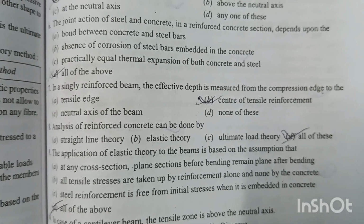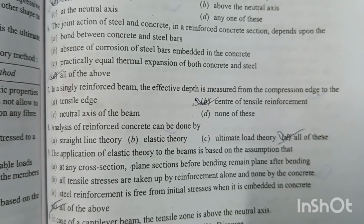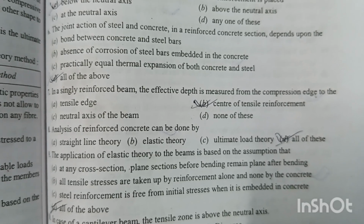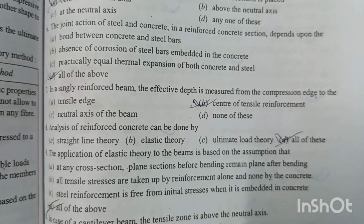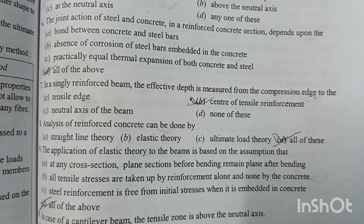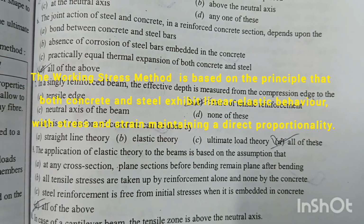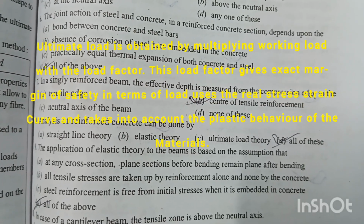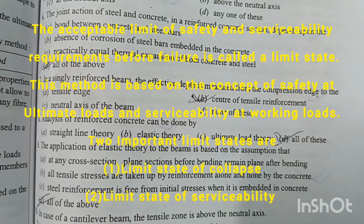Question number 8. Analysis of reinforced concrete can be done by option A, straight line theory; option B, elastic theory; option C, ultimate load theory; option D, all of these. Option D is the right answer. Straight line theory and elastic theory are also called the working stress method of design, and ultimate load theory means the limit state method of design.